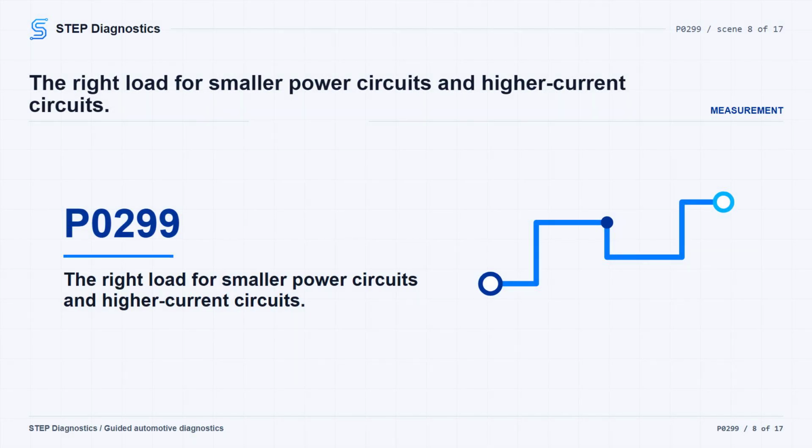For a power-providing circuit carrying approximately 200 to 10,000 milliamps, load the circuit with a 250 to 350 milliamp test light and measure circuit voltage with a DMM while the test light is connected. As a guide for circuit size, conductor sizes 24 gauge, 0.5 millimeters, or smaller are generally used to carry approximately 1,000 milliamps, 1 ampere or less. If voltage drops during that load, suspect excessive resistance.